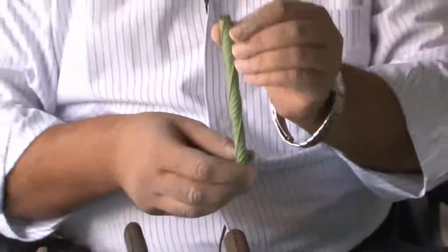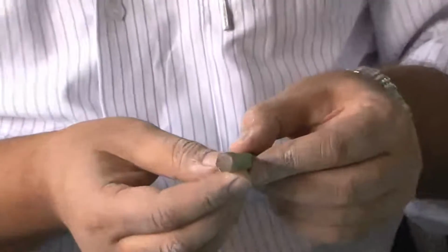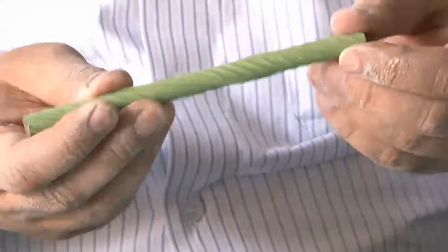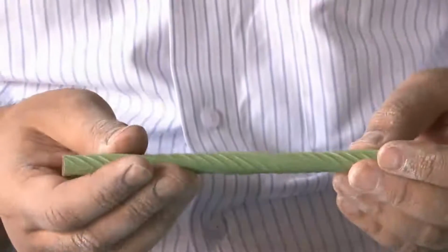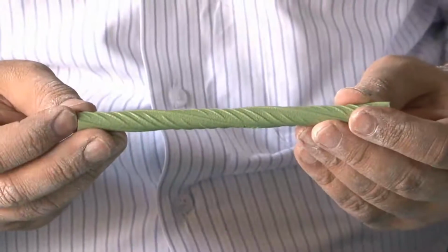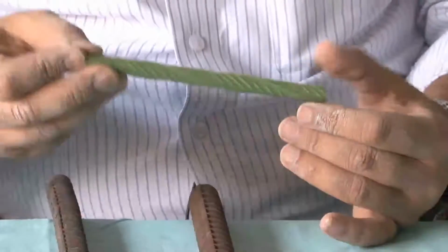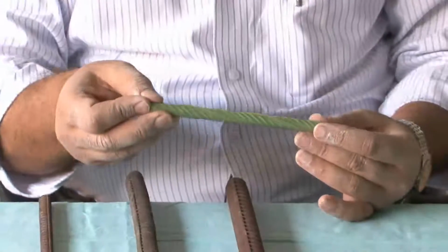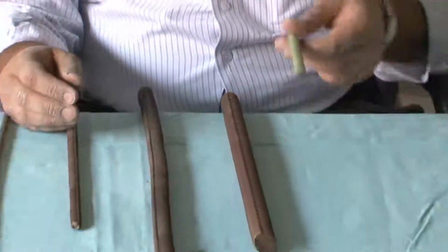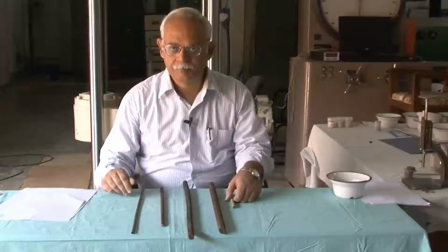And here you will see that it is nothing but a normal steel bar, except that it has a coating on the surface, and this coating of epoxy on the surface of steel helps prevent any direct contact between the atmosphere and the steel, and therefore, the life of this steel bar is much longer than that of normal steel bars. Of course, they become a little more expensive than the steel bars.